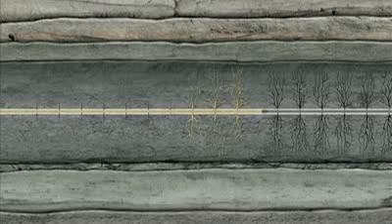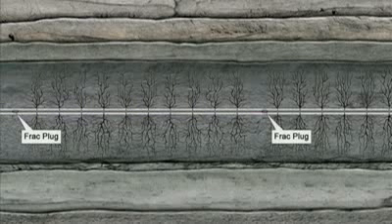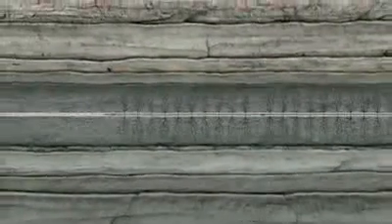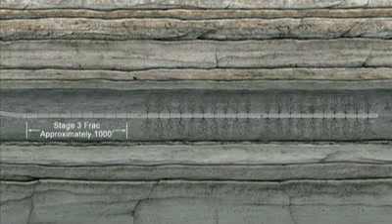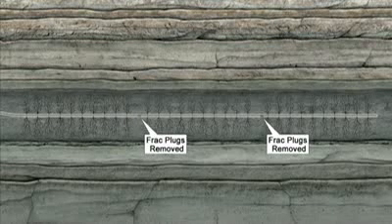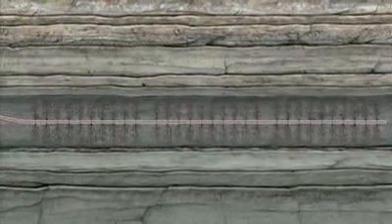The process of perfing and fracking can be repeated several times along the horizontal section. Once all fracking is completed, the plugs are drilled out to allow the gas to flow up the wellbore. The last stage is then to install a new wellhead known as a Christmas tree on the surface, accompanied by other surface equipment that allows further testing and evaluation of gas properties. Our experience shows that thanks to the application of modern technologies, we can extract shale gas safely, efficiently, and responsibly. It is becoming a highly productive source of energy around the world.